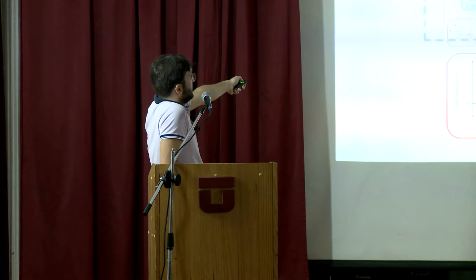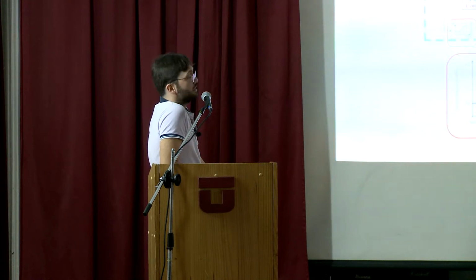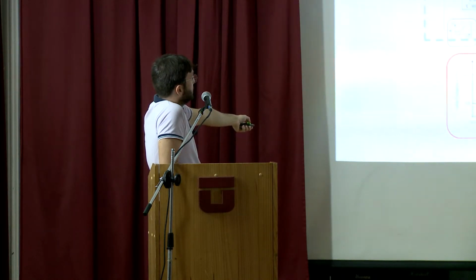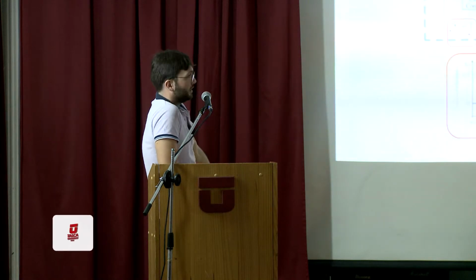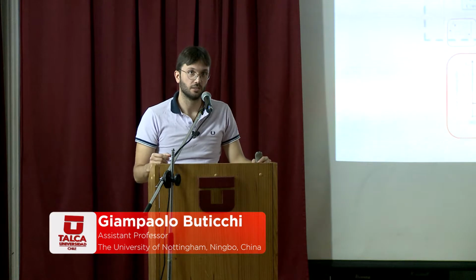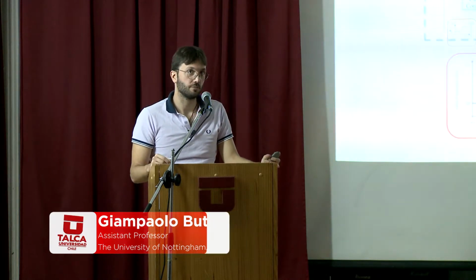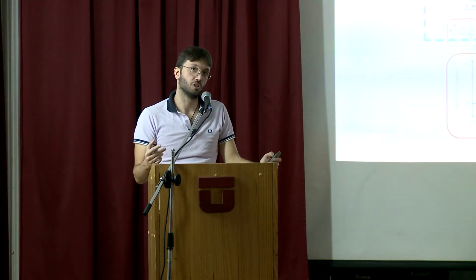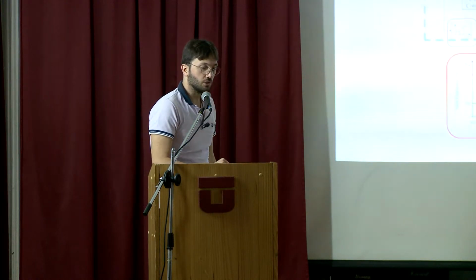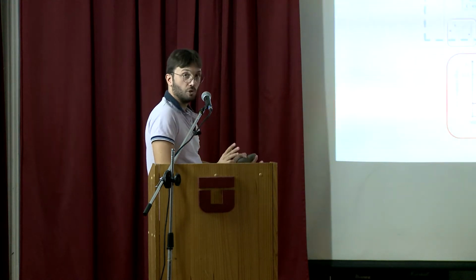I can say that I measure the DC-link voltage, and then I have a lookup table. If the DC-link voltage increases, then the output of this lookup table is a frequency that changes from 50 to 51.5. The integral of the frequency is the angle, let's say, there is the 2 pi factor, and this angle can be used to generate my 3-phase voltage references. So there is no communication in this.